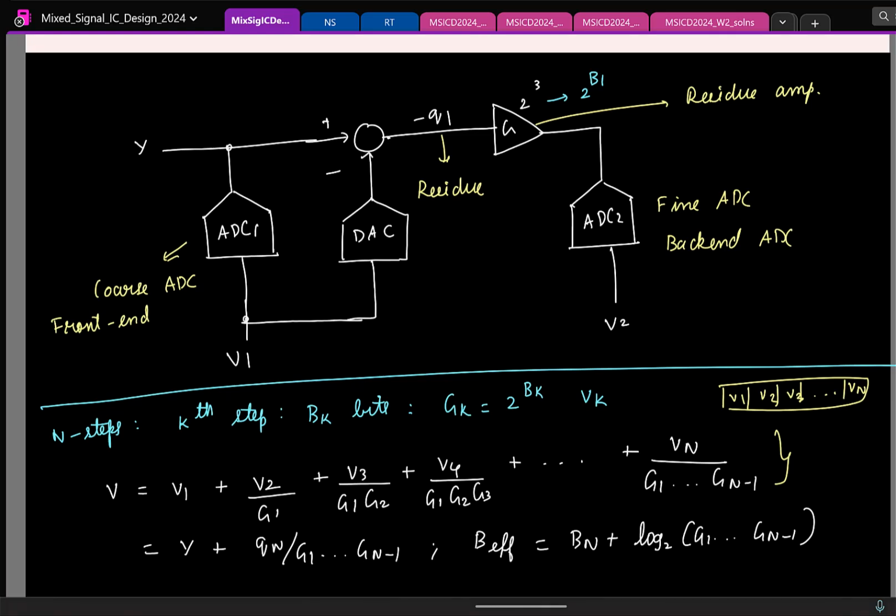So the DAC doesn't have any mathematical noise being added, at a block level. At circuit level, yes. Basically, the DAC is simply taking digital codes 1, 2, 3, 4 and translating them to voltages. That's all. So ideally, it will not add noise, unlike an ADC, where the moment you digitize, you have a quantization noise. This process, in principle, has no error. In principle, it is basically taking the code and multiplying with the voltage. It's a linear process.